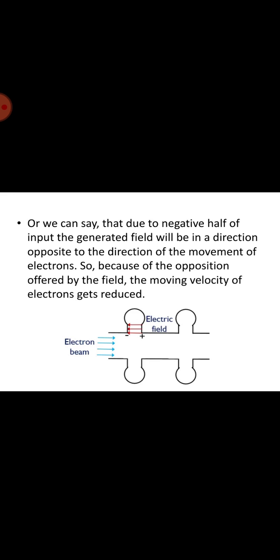For high power cases, a DC solenoid coil is wrapped around the interaction space or electron path. Klystron magnets are usually called focusing elements. Loss of magnetic field can be disastrous. In cases where the focusing element is an electromagnet, sensing circuitry is usually provided to rapidly shut down the klystron in the event the magnet is lost or other faults cause the loss of magnetic field.